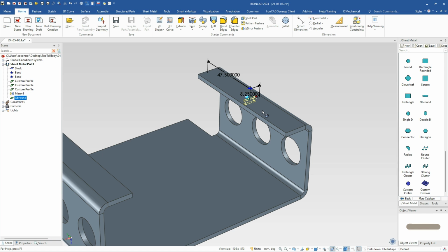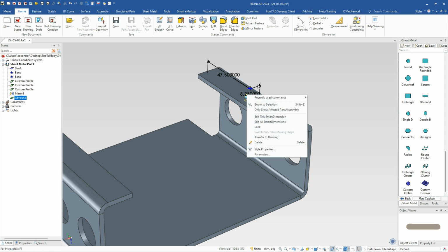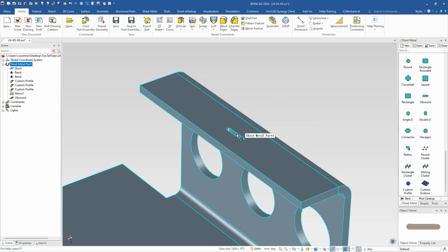slot feature here, and we're just going to use the tri-ball again, orient it the right direction that we want. I'm just going to drag that to align to this edge inside of here, and then when we select our feature, we can go to this little handle here and say tooling features. Sorry, let's zoom in so you can see this better.